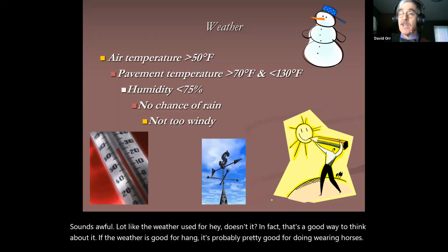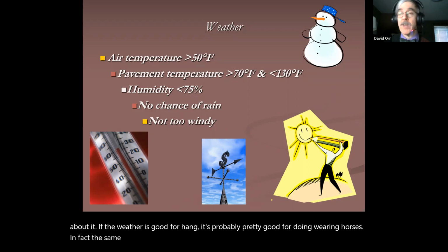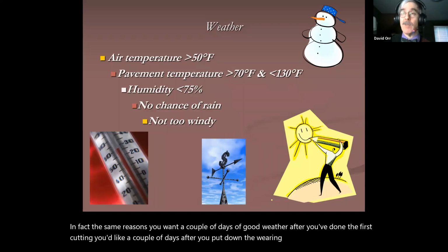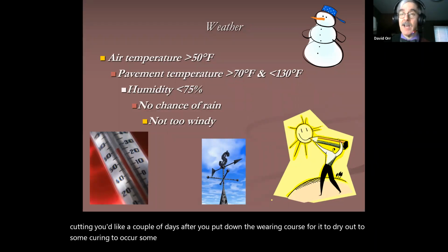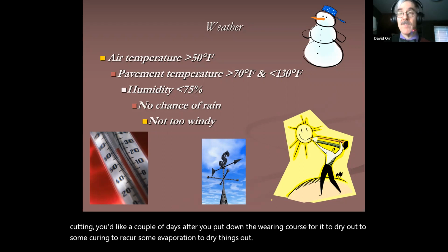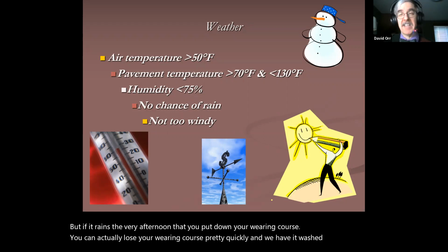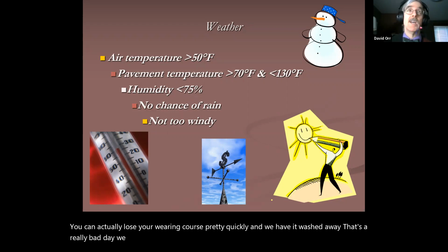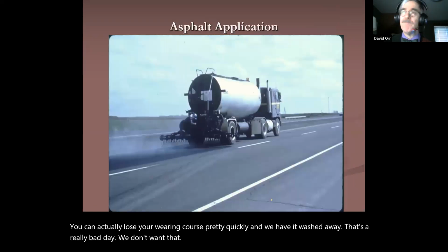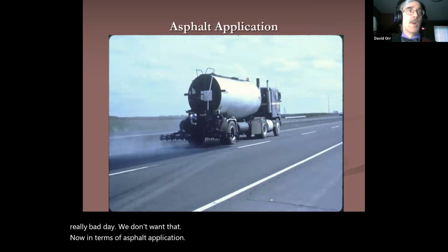In fact, in the same reasons you want a couple of days of good weather after you've done the first cutting, you'd like a couple of days after you put down the wearing course for it to dry out, for some curing to occur, some evaporation to dry things out. Because if it rains the very afternoon that you put down your wearing course, you can actually lose your wearing course pretty quickly and have it wash away. That's a really bad day. We don't want that.